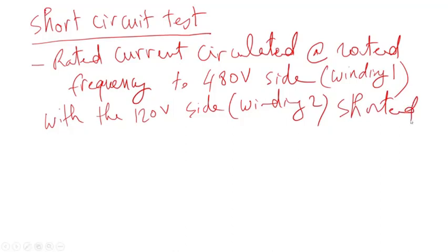And this is basically how practically the test is done on transformers to determine load losses and also impedance, the positive sequence impedance.